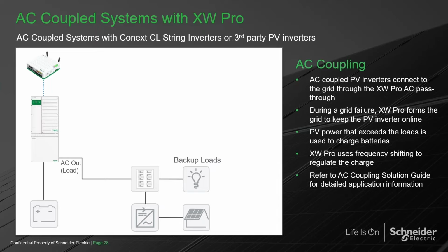It's going to start its countdown, the 300-second countdown, and is already measuring the voltage or frequency on this backup load. And once the 5-minute countdown goes to 0, it goes into its normal operations. Hey, the grid is here, I'm going to get back to work. And it's synchronized to the sine wave of the XW Pro and starts injecting current into the panel.